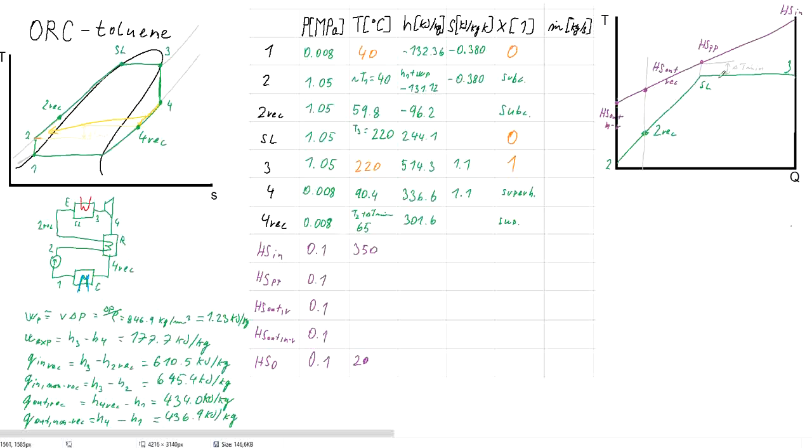So you can already probably see that it will not have any effect on the mass flow rate in the organic Rankine cycle. Therefore, regardless of the recuperation presence or not, with the same heat source parameters, we will get the same power output, unless there is some limit below which we could not cool down the heat source. So the recuperation in the waste heat recovery does not have its justification.